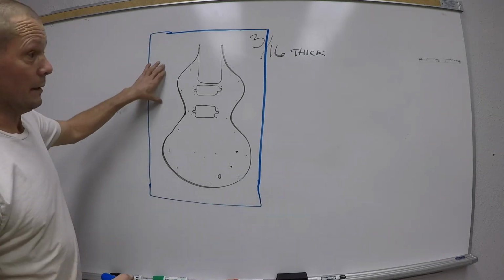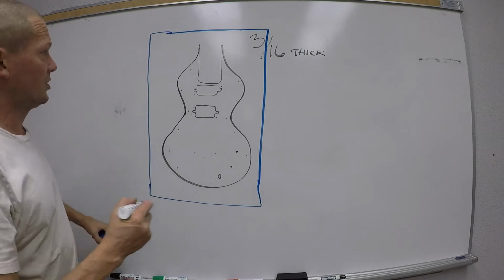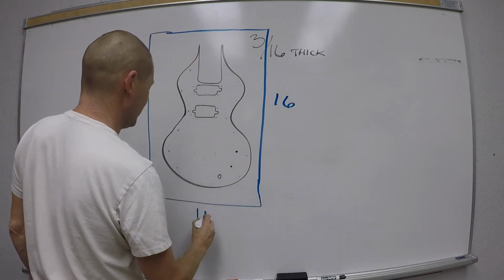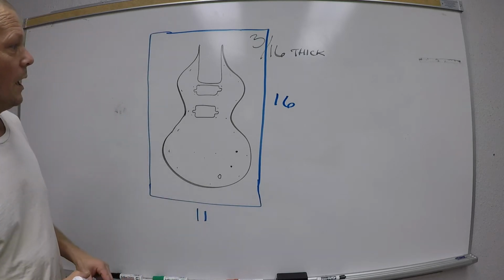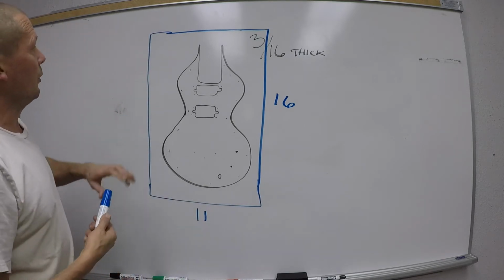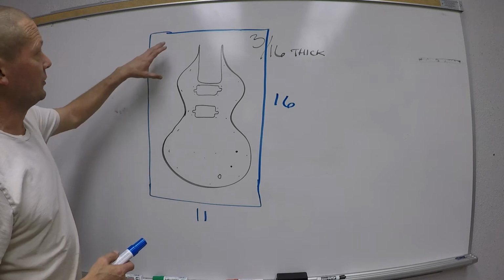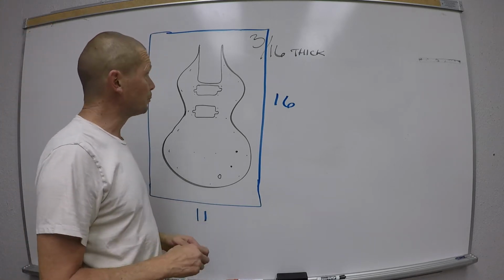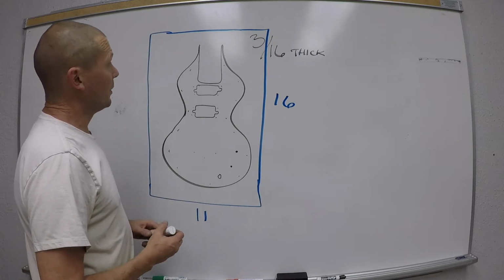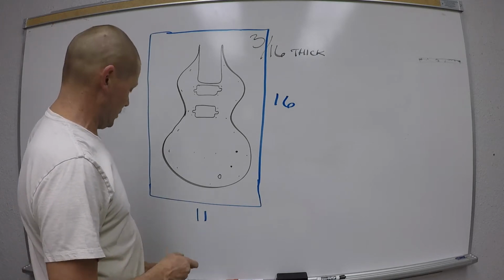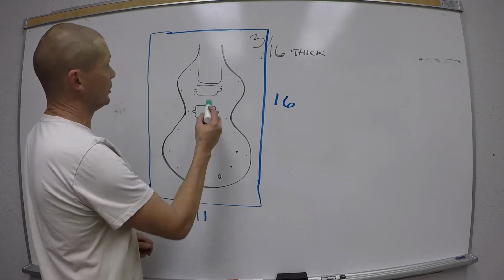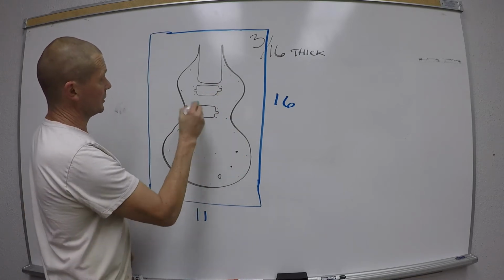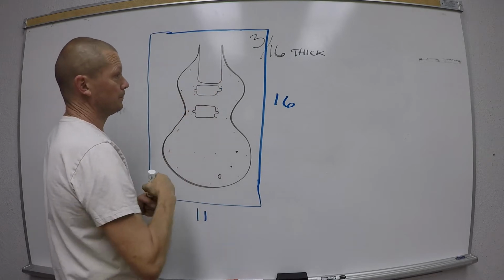And it's a plate, 16 by 11, I think is what it is. We're not going to use the vise. We're going to hold it down with step locks, which I'll show you. But the order of operations is going to be coming in with a center drill and center drilling all the holes on this plate.